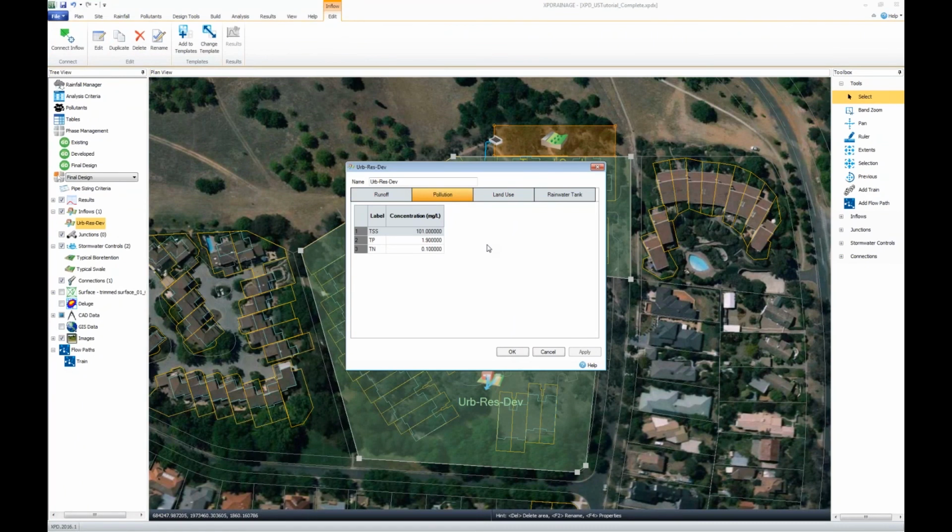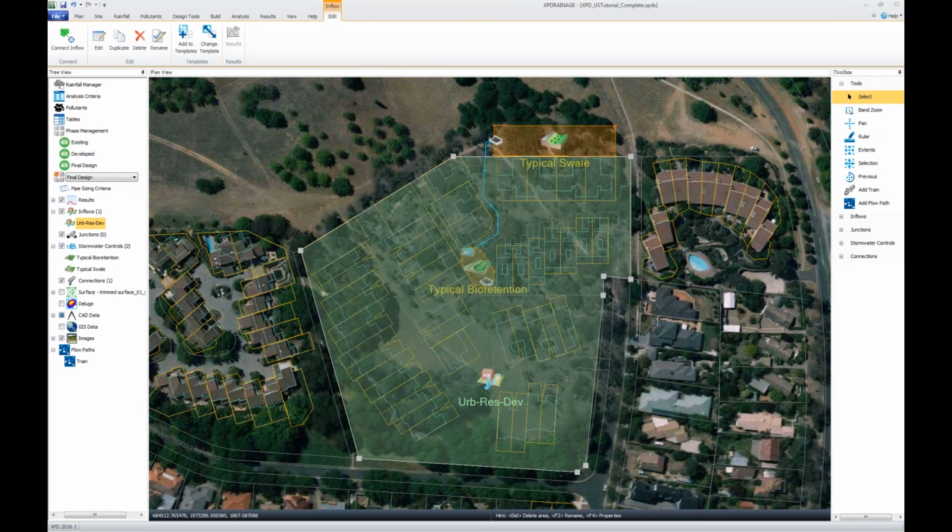So this one I actually had some local runoff wash-off rates. So here would be my suspended solids, phosphorus, and nitrogen. Pretty common three. Maybe often it's just suspended solids. I think in the question it was looking at phosphorus. So this perhaps is the wash-off, just milligrams per liter from this site. So that's what this area would represent.